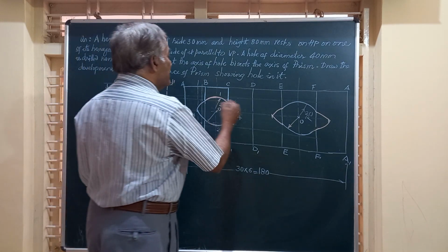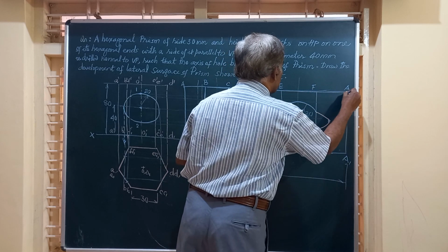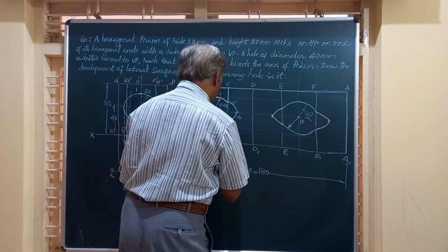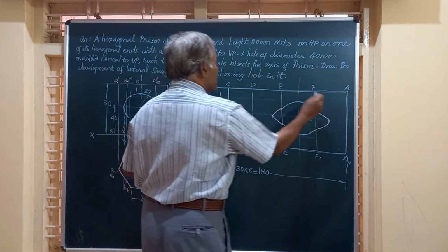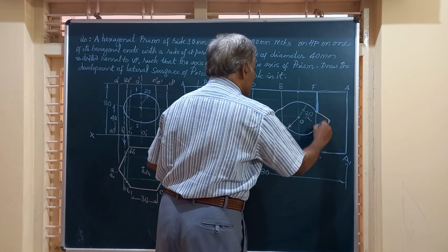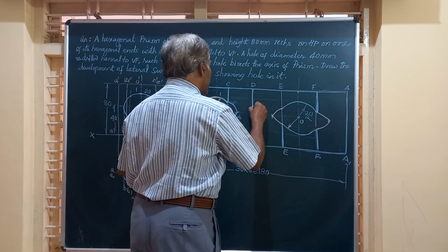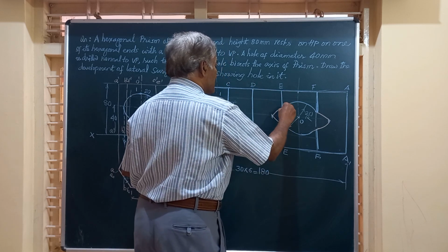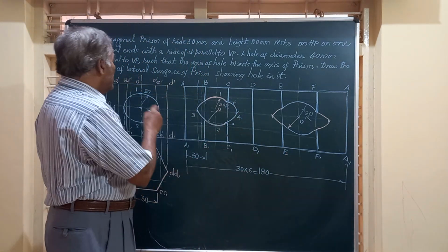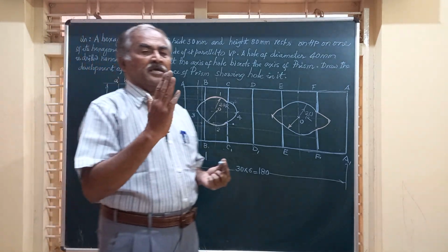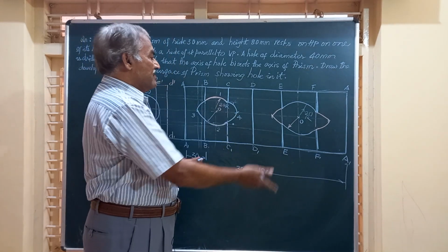Friends, after completing this, let us darken the borders, the outlines of the figure, and again at the bottom you can have it. Here, this has to be darkened up to here. Have to darken that. This is to be shown by vertical line DD like this. And friends, this is how the hole drilled on the hexagonal prism perpendicular to the plane of the board looks in the development.